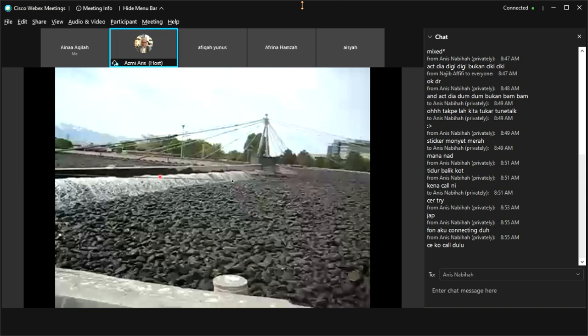Another point that he raised is that the distribution of the holes that release the wastewater is not uniform. You will have more holes at the end of the distributor and fewer holes towards the center, because the area within the center is small and it gets bigger as it goes to the end of the rotator. So here it needs more holes so that more wastewater will come out from this side, so that they can distribute the wastewater uniformly.